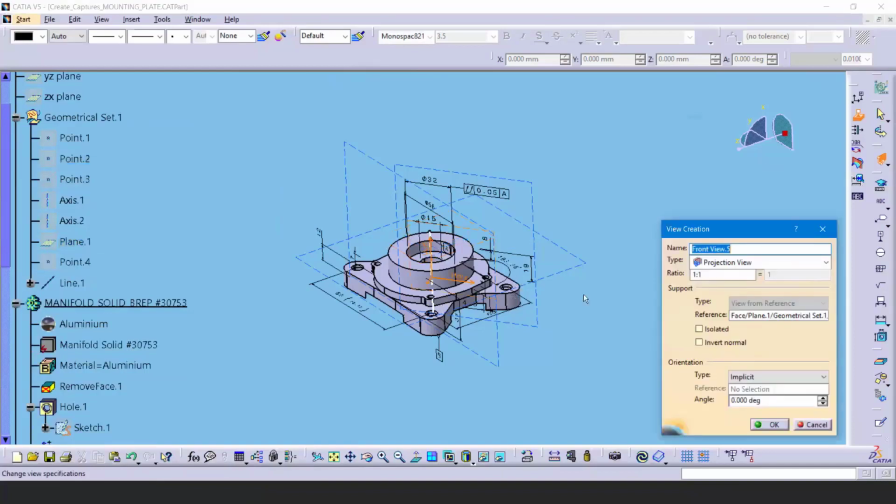And then here's the takeaway from these options, the projection, section and section cut. These are going to play importance in their differences if you're actually using a separate drawing file for it. So projection view is not going to cut through anything. Section view is going to cut through things, and it's going to show the information in the background, whereas a section cut is going to cut through it but not show any of the background information. If you know you're eventually going to be using these for a separate drawing, then you would want to make sure to set these up properly.